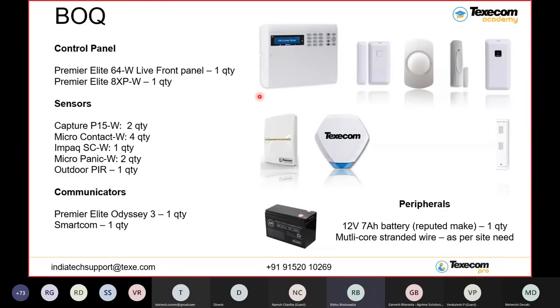Some are wired, but most of the sensors are wireless. Then number three, we have to give wireless expanders on each floor, because note down this point: for every 2000 square feet area, especially for residences, we have to give one wireless expander. All these points I have derived from my site survey.